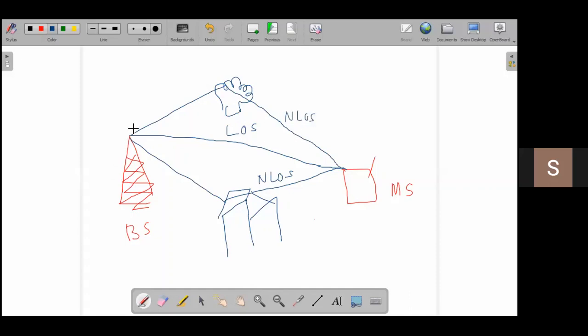See, the same signal is transmitted through different paths. This is called multipath, and those are added together at the mobile. This is called multipath interference, and it creates only one signal by adding together. The signals may add constructively, increasing the strength of the signal by adding positively, or destructively, reducing the strength of the signal.